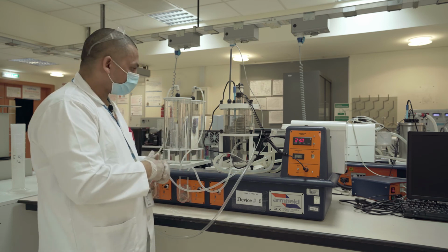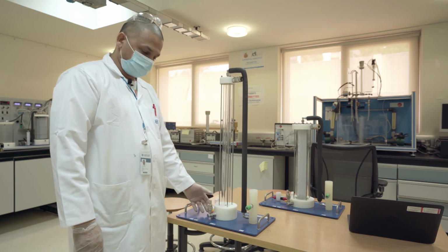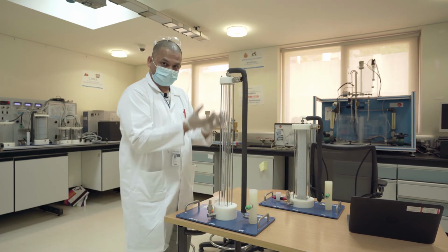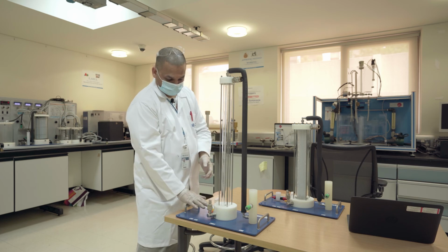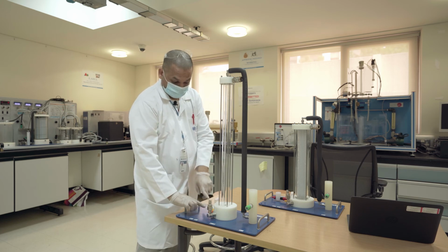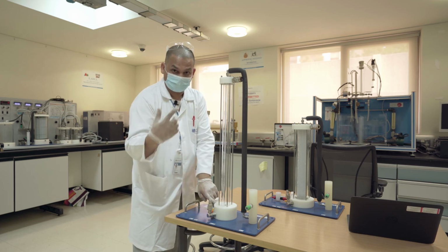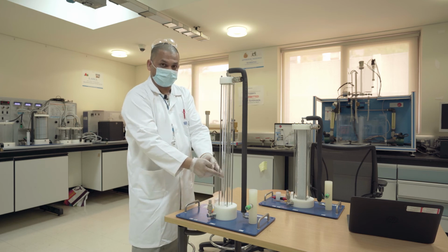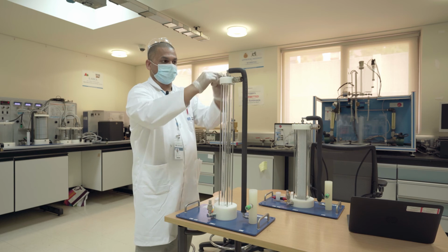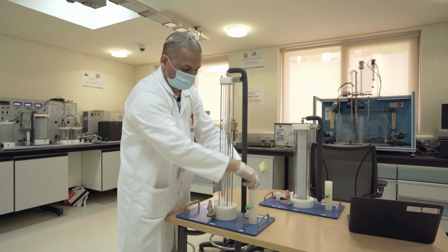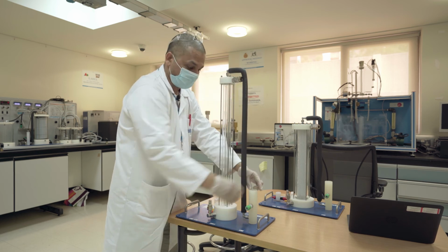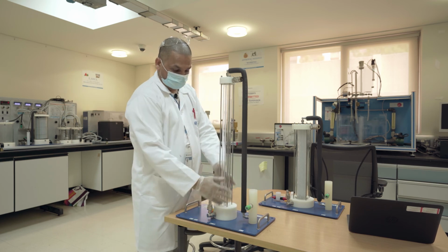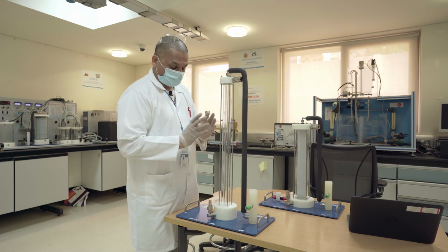So this is my laminar reactor here. You can see there is a vertical tube in which I am going to flow my 2 reactants in order for them to react. Both A and B, the ethyl acetate and sodium hydroxide, are entering at the bottom, flowing under pressure and going up and out from here, and then we are measuring the conductivity here. This I can put in the other setup to connect that one. That's the only thing.